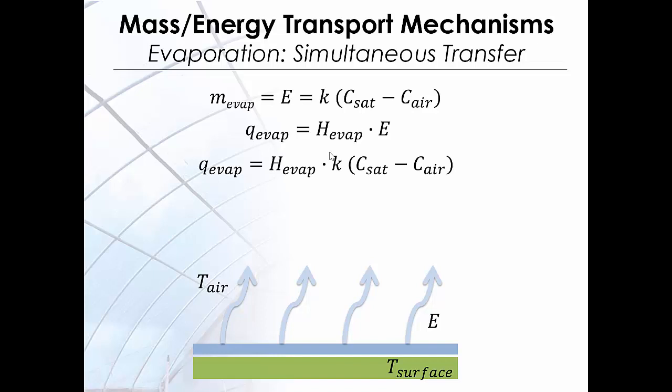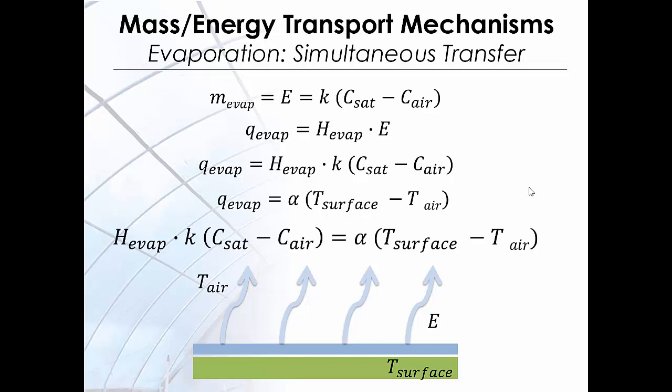Based on the equation for vapor flux density, assuming that this vapor flux density is the result of evaporation, then the total heat required for said evaporation can be determined by the equation presented here. This energy is extracted from the surrounding air by convection, and this localized energy balance then becomes an equality, as you can see with this equation. Using the previous Nusselt and Sherwood relations, it is possible to determine the convective heat transfer coefficient, the alpha, as well as the mass transfer coefficient K.